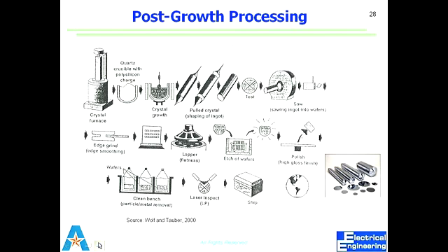We do use both side polished as well, but that is a technology used in industry. Industry uses both sides of the wafer. They don't want to miss any semiconductor material to make devices. So they are double side polished. And there is a special type of those wafers. We'll look at those. They are called SOI, silicon on insulator wafers, which are double side polished.